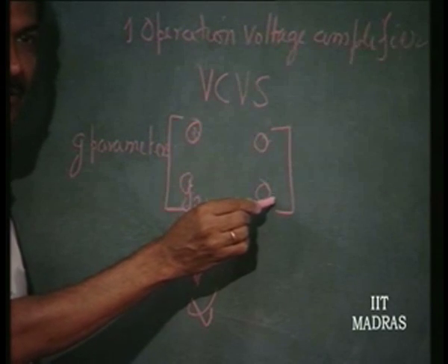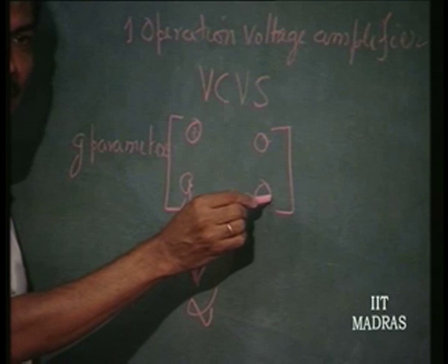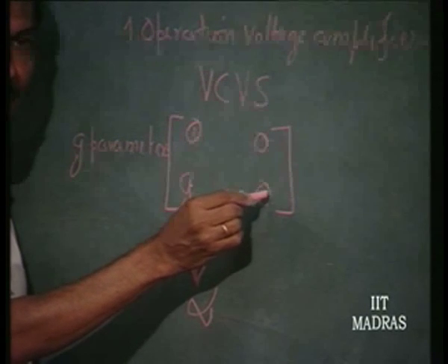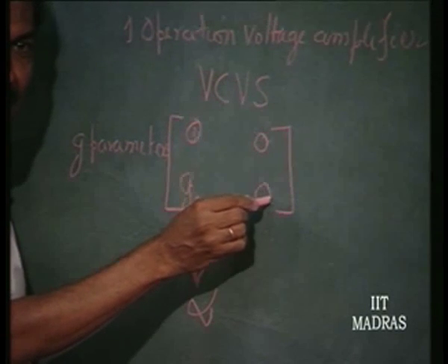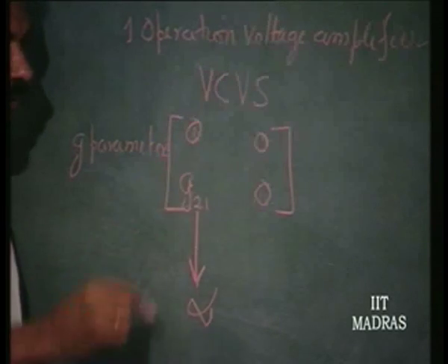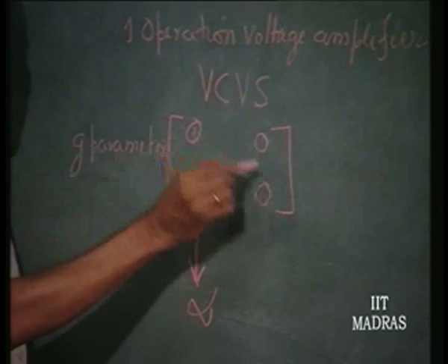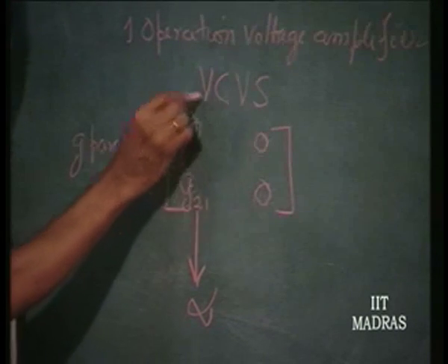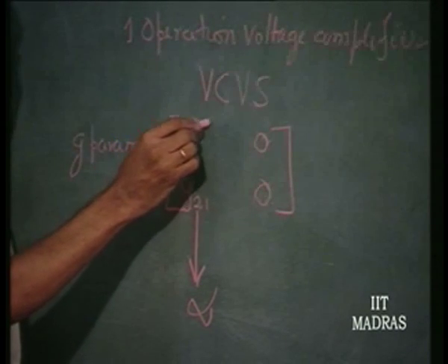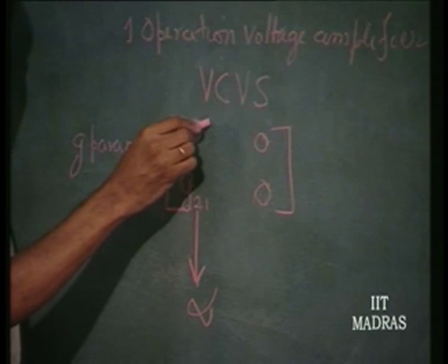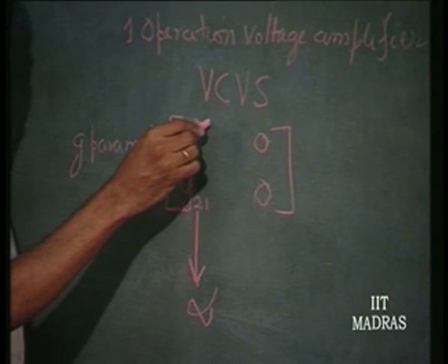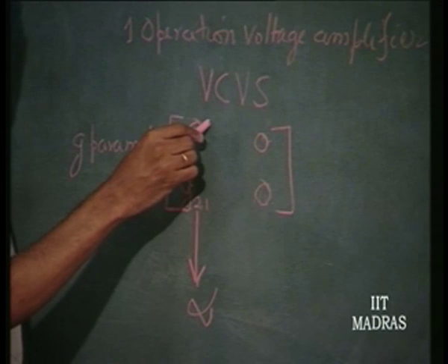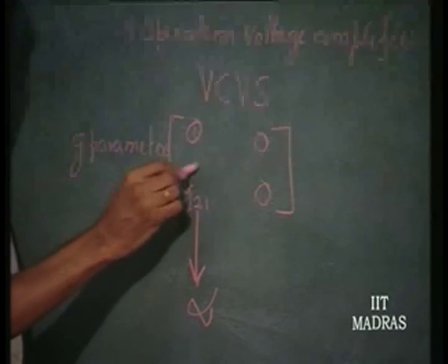Here we have to decrease the output impedance or output resistance. So, we have to take suitable measures to do this. Now, this can be done, we have seen earlier, in designing differential amplifiers, which will be the input stage of any operational amplifier, let us say differential input, by operating at